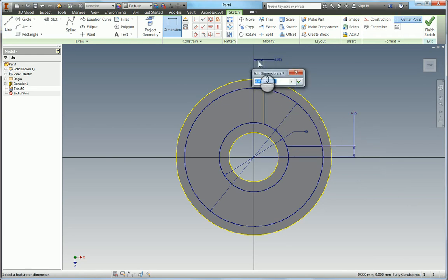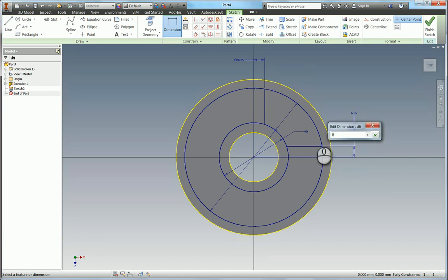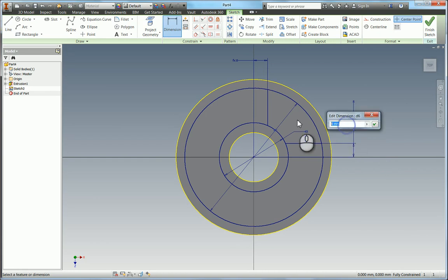So what you can do in Inventor is you can actually select other dimensions. So if I select this, you can see it's changed to D6, so that means whatever this one here changes to, say we change that to 8 millimeters just to show you, they both change. So this is a function of this dimension. So again, we're modelling parametrically in case anything changed at the end.